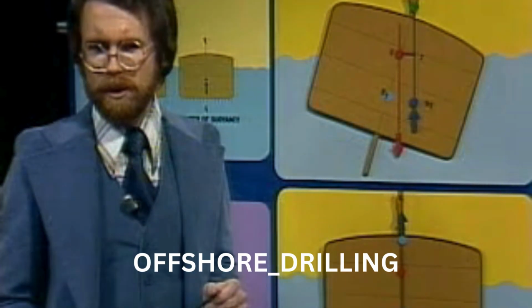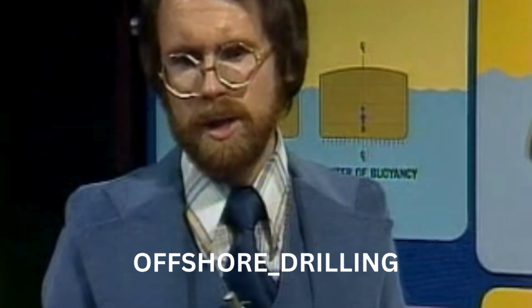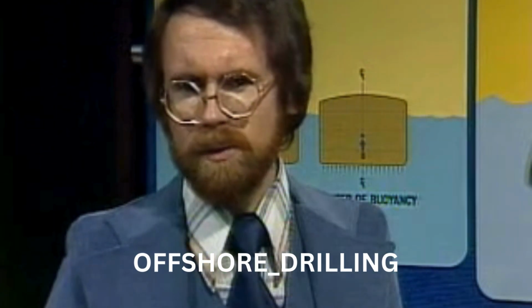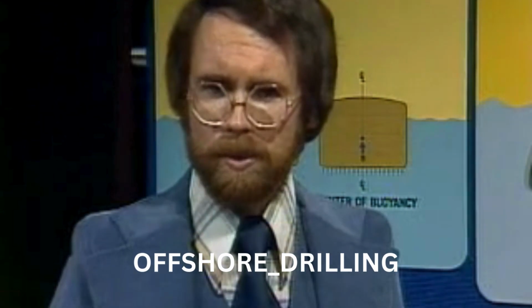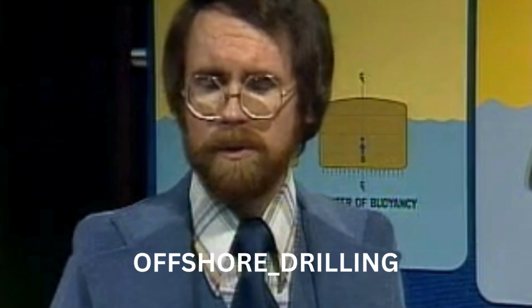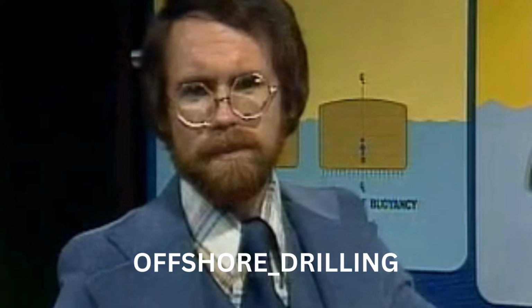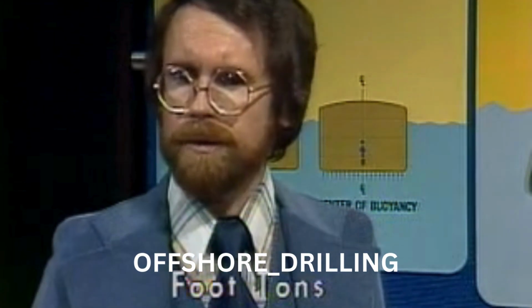As we talked about earlier, a couple is expressed as a certain force times a distance, or a moment. In the case of a vessel that has been inclined or tilted, the moment or couple is expressed as the weight of the vessel, its displacement, times GZ. In the case of a vessel, this moment will be measured in foot-tons.